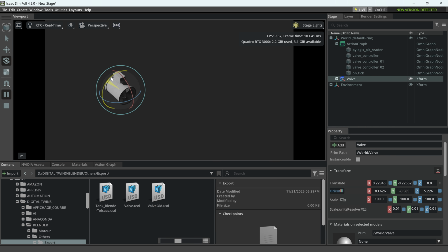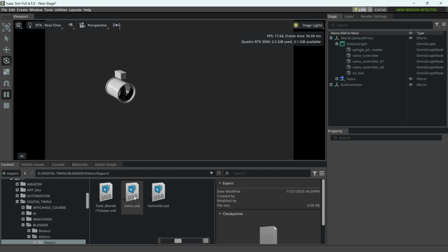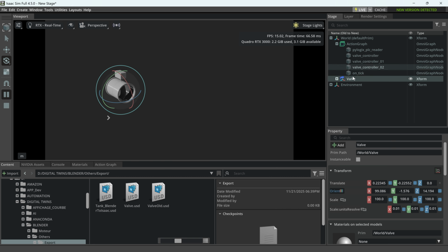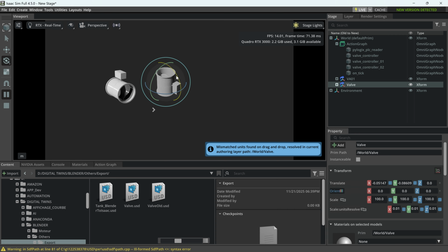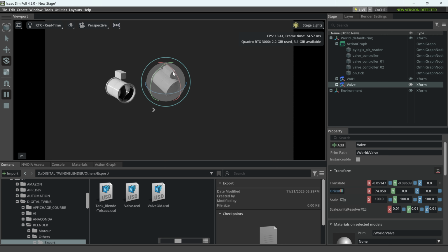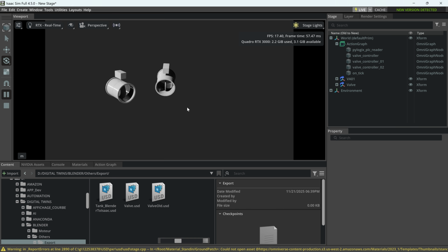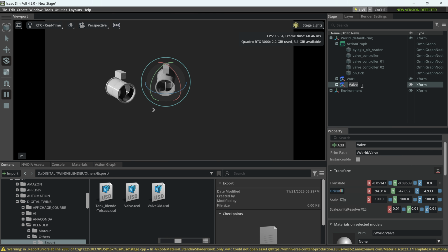The idea is simple. Instead of writing a custom script for every valve, we build reusable industrial objects that can be instantiated across a system. In automation, we don't rebuild logic from scratch for every device. We define a function block once and we reuse it everywhere: pumps, motors, valves, sensors. That's what makes real industrial systems scalable.